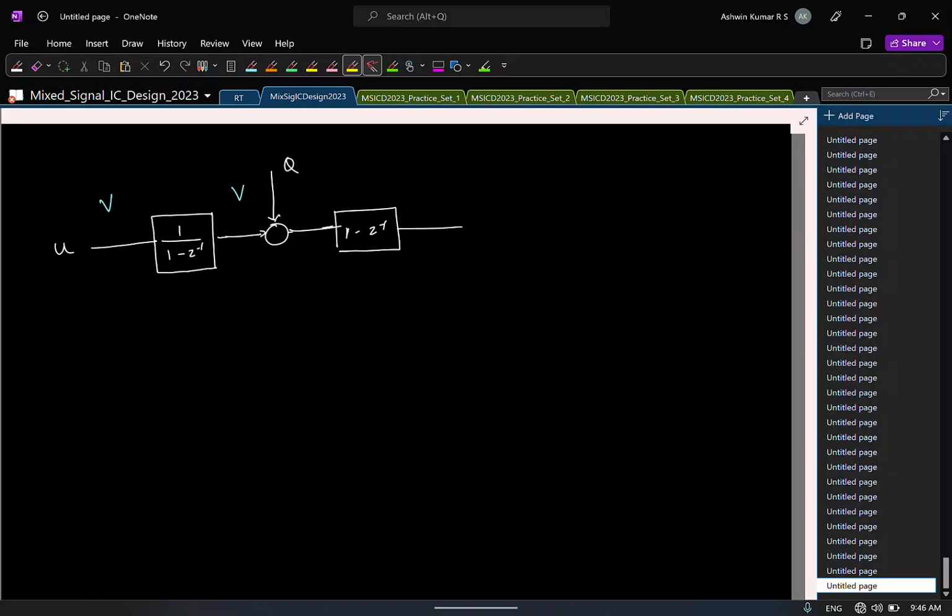So let's see if something else can be done here. Do you know any quantity, with respect to voltage or current, the issue is after some point it saturates the supply you have, right? With a DC input voltage, the integrator output will saturate to your supply voltage. That's the issue.